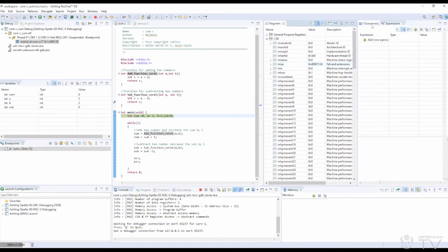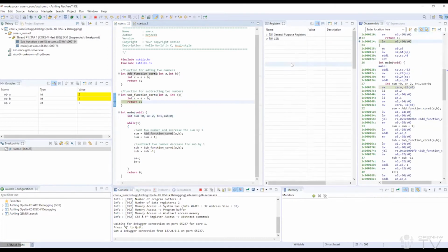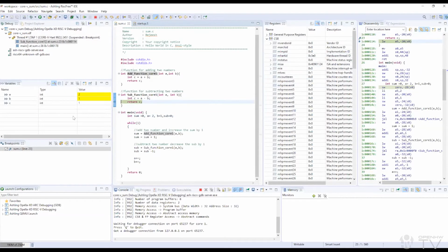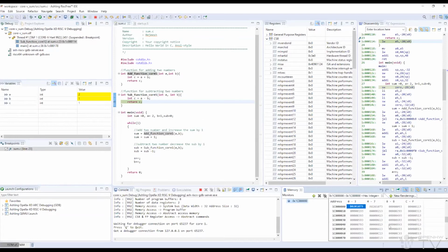And obviously we have the disassembly view. And all the basic views, like the variable view, showing the current variables, and the breakpoint view. We can see I have already set a breakpoint here. Maybe I'll just run and see. That breakpoint has been hit and the register values are updated. All the views are updated. And then we have the memory view. This 1C0 range is our RAM area. We can see the RAM data has been updated. So memory view, registers, disassembly, variables, breakpoint view.